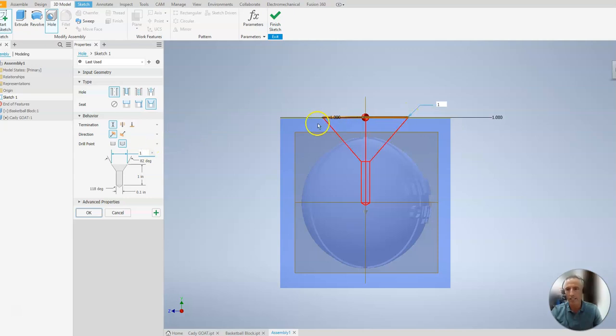And you'll see I have a nice big opening, so I'm pouring the chocolate in. It's going to be easy to get into that funnel. But the problem is the funnel is going to leave an imperfection on my basketball. To give you an example of how this works, anytime you have an object like this gum container that was plastic injection molded, you'll be able to feel seams on it, which it does have seams on the sides, and usually an injection site on the bottom. They put it on the bottom because it doesn't look as good, because there's imperfections.